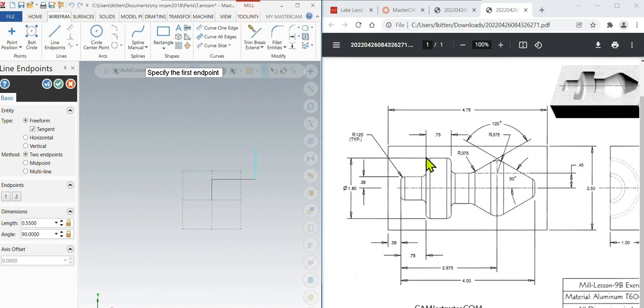Okay, so now we're sitting at this corner. Now we pick on the next one and keep on working our way around. Now we need to go 0.75 plus 0.75, right? So we go space bar, so that'd be 1.5. 3/4 plus 3/4 is 1.5 inches. So 1.5, comma, and we're still at 0.9 tall, so 0.9. Okay.